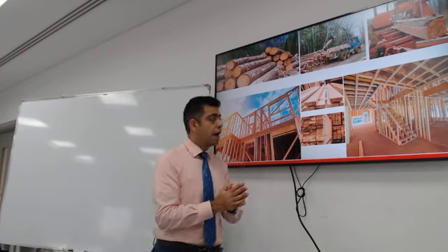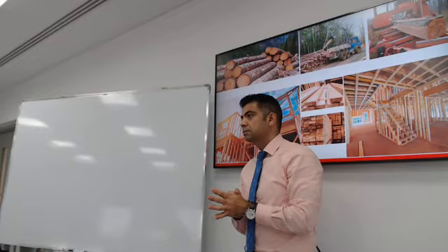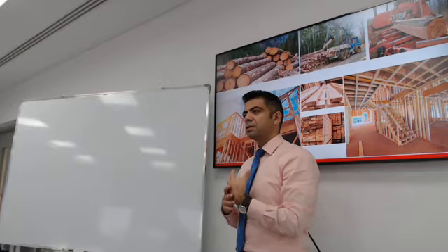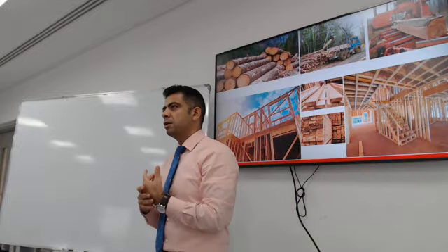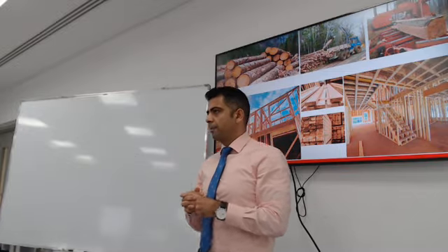How tall, how far can you build a structure entirely from wood? Two stories. That's about it. The tallest I personally designed was 3. I think you can go maybe 4 or 5. It depends on the spans, obviously. More than that, you need a different structural material.